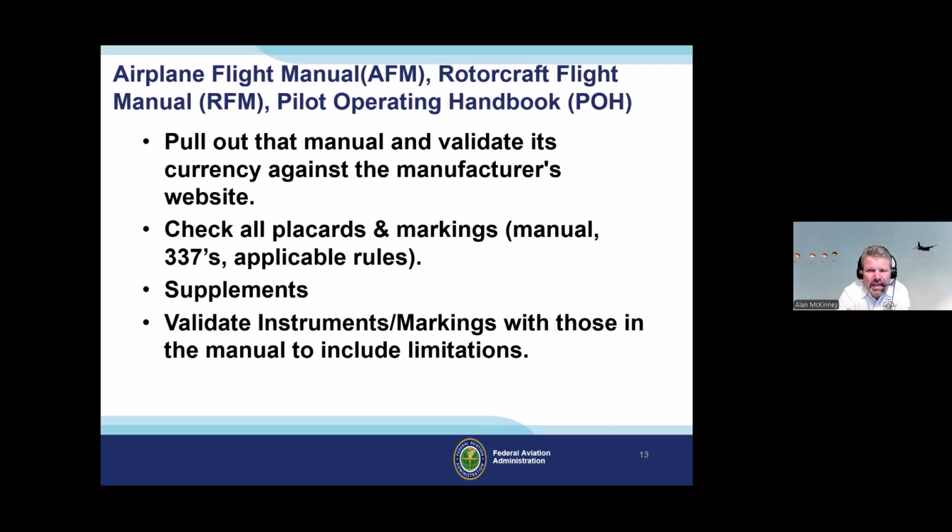So let's say that the aircraft you purchased had a mechanical landing gear to extend the gear. So it has an electric motor with jack screws and a bicycle chain and gears to extend your landing gear. But as that production went on and we learned things, they got away from the old electric motor with jack screws and the bike chain and the little sprockets, and they went to a hydraulic system.